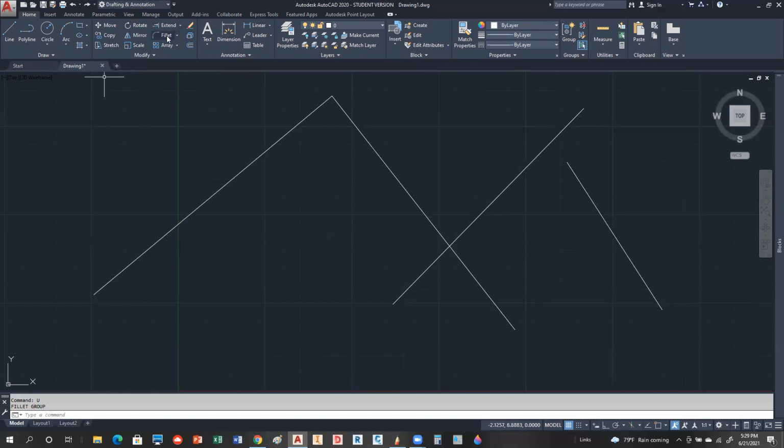Okay. So for instance, if I went here and I set my radius to, let's say 20 or 10, I bet mine's going to be too big too. Yeah, and that's what it's telling me. It's too big. Okay. Did it work now? Yes, it did. So if you get that, it can't fit it in here is what's happening. And it's not going to second guess it. So that's the one thing about it. So I'm going to set mine to a value that does work, and I'm going to go ahead and fillet it. Anybody else have questions? That was a really good question, actually, Ian, because that does happen.